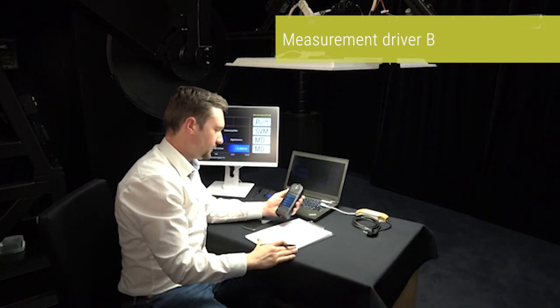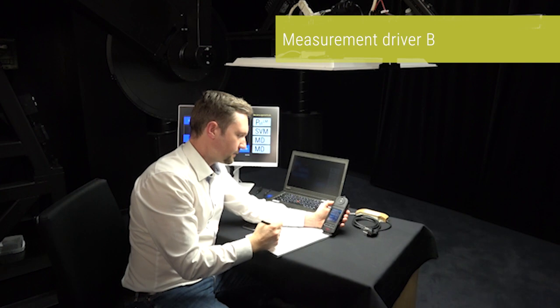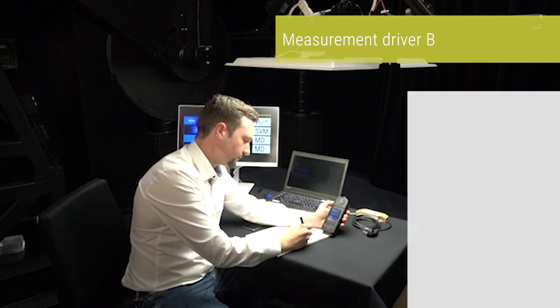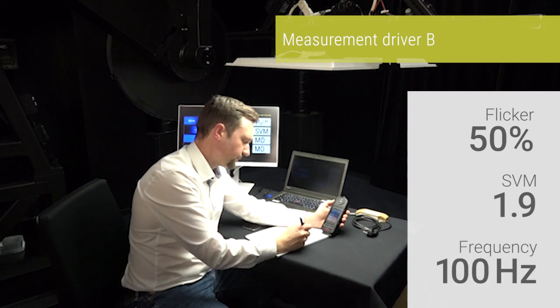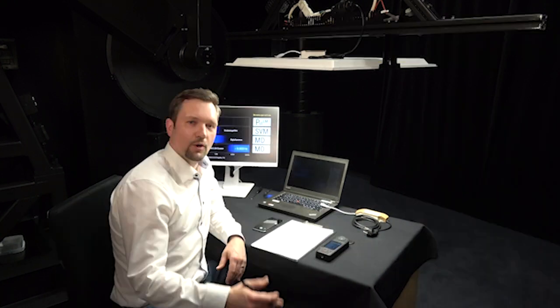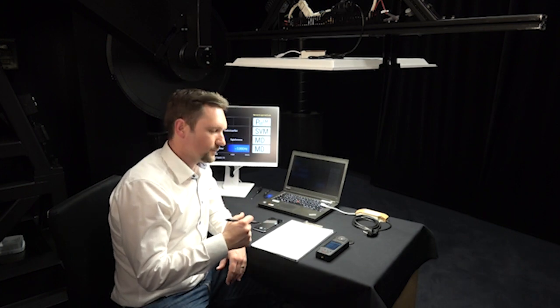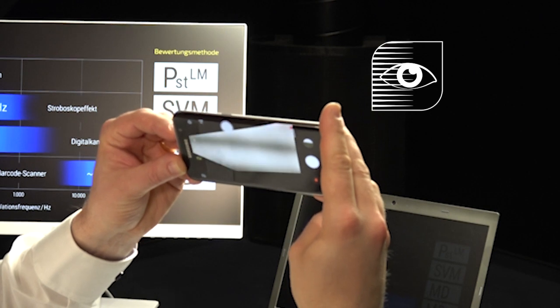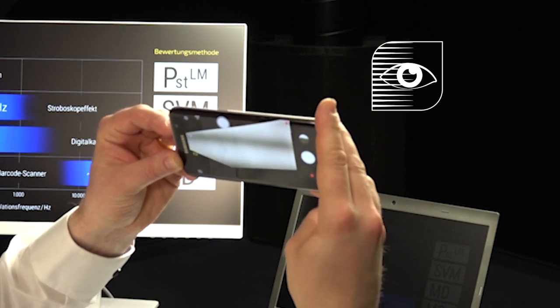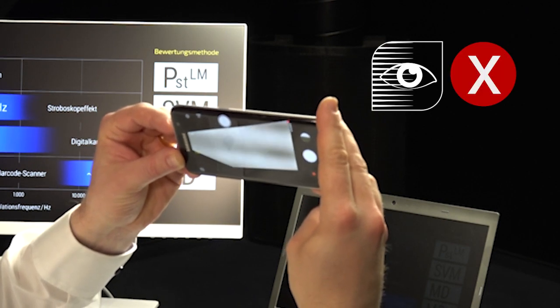This is already conspicuous. Immediately, you can see that the flicker percentage is 50%. The SVM value is 1.9. Now let's also check the driver with a cell phone camera. Driver B is clearly different from driver A. Taking a good picture would be impossible.